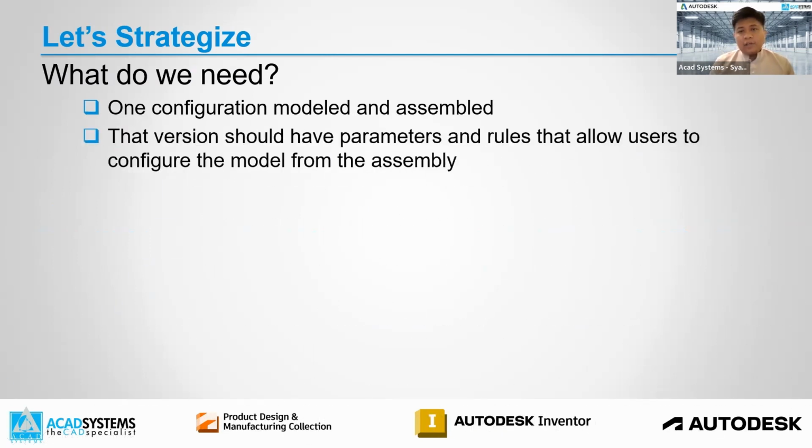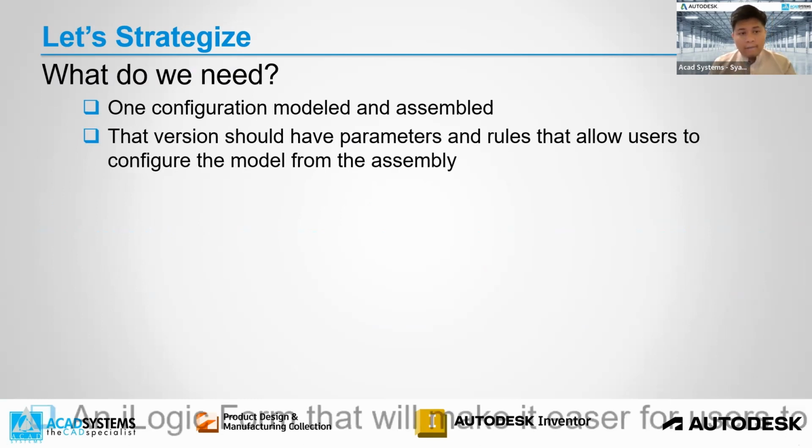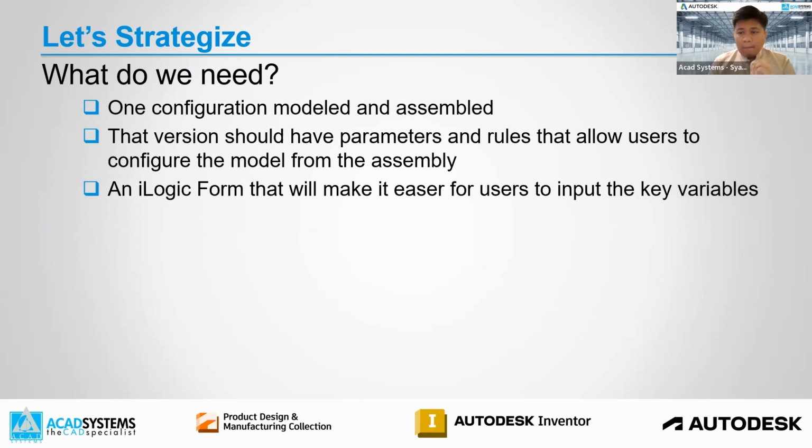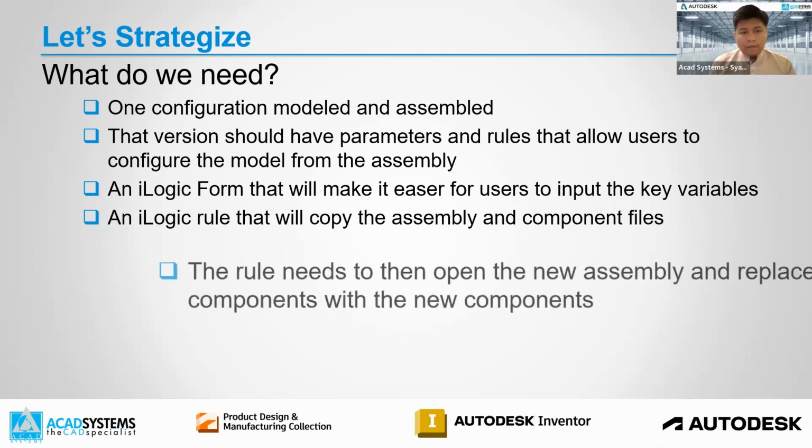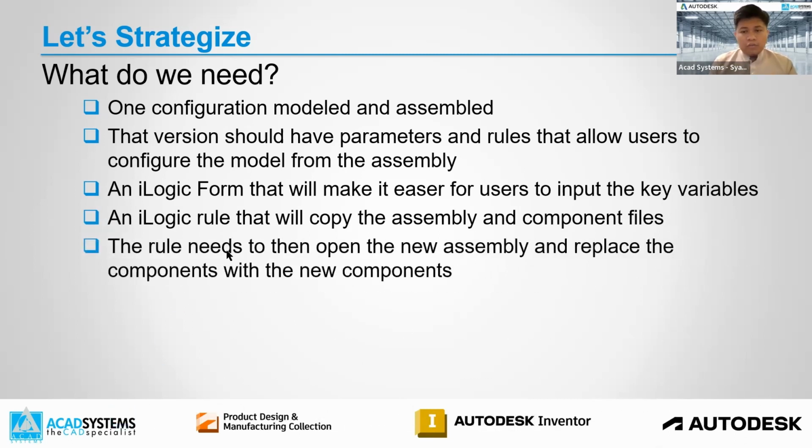The second strategy, for every version that we created, we need to make sure that the parameters and rules will be saved in here directly. So an iLogic form, you need to create also. Try to minimize the buttons to make it easier. The rules will be a bit complicated for assembly, but it's okay, you can learn. The rules need to open and replace the component with the new component.